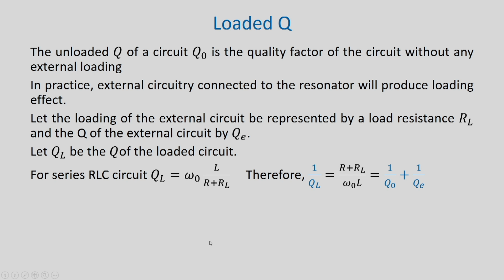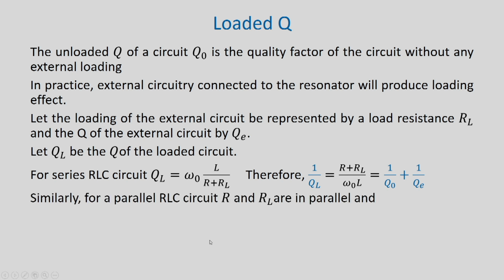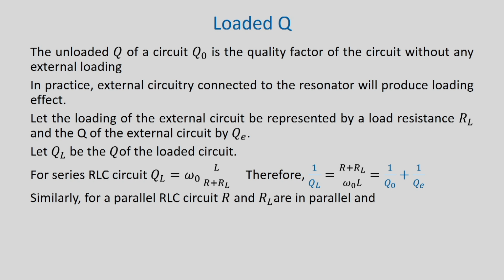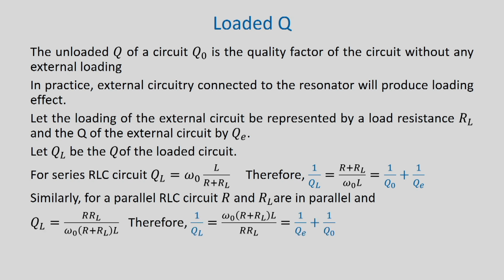Let us now consider the parallel RLC circuit. In case of the parallel RLC circuit, the external resistance RL will come in parallel with R, and the effective resistance will now be R into RL divided by R plus RL.